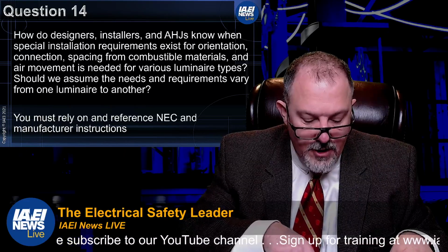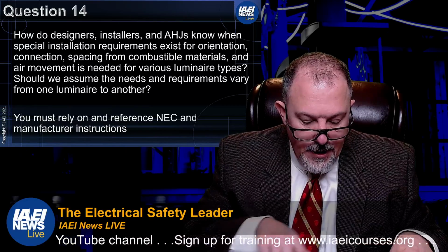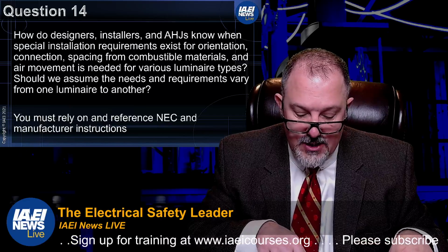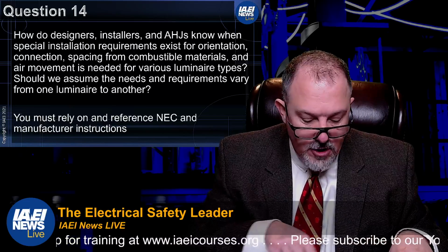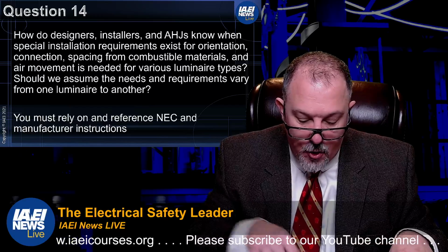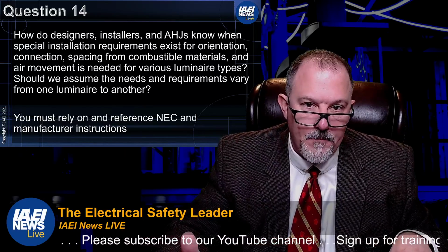The electric discharge in A says independent of the outlet box. Access to boxes: electric discharge and LED luminaires surface mounted over concealed outlet, pull, or junction boxes, and designed not to be supported solely by the outlet box, shall be provided with suitable openings in the back of the luminaire to provide access to the wiring in the box.